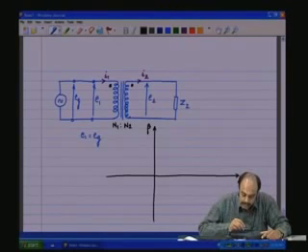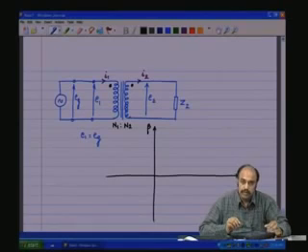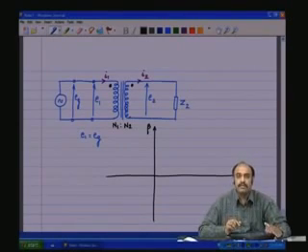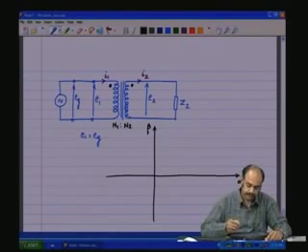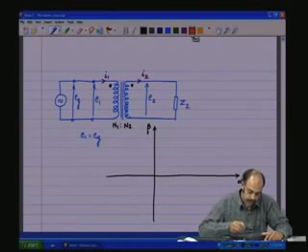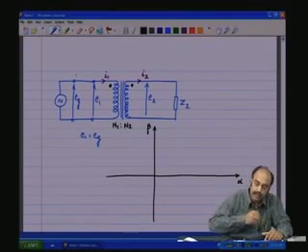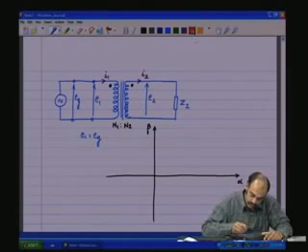So, we need to choose some reference phasor along this direction, and remember that phasor means same as the vectors, except that the amplitudes are effective values or the RMS values. Now, we shall choose the input voltage as the reference direction, that is, the EG direction that we are choosing.